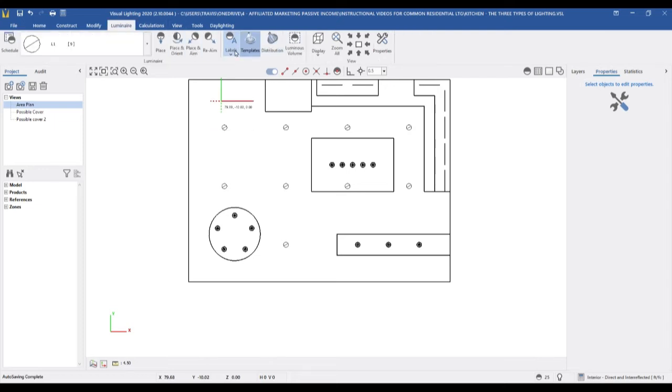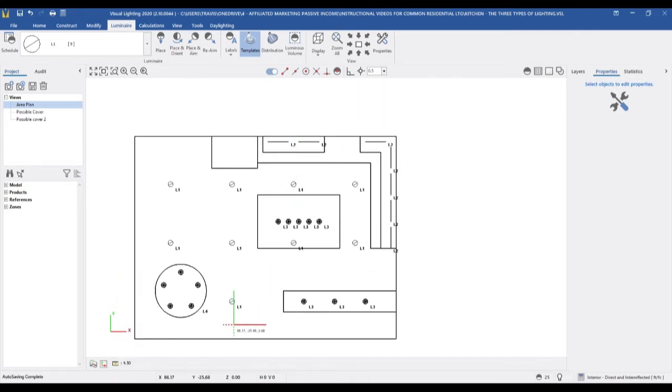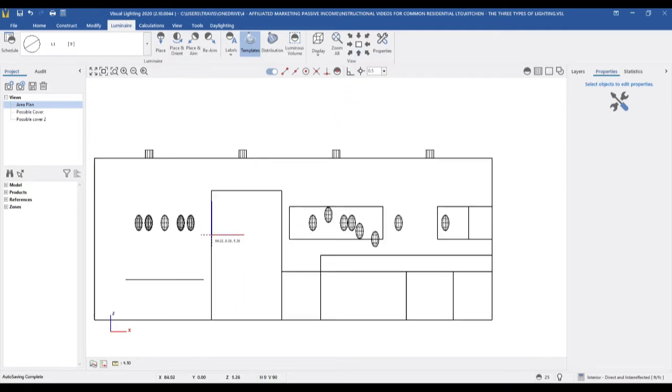If your ceilings are shorter, I like to use 4-inch just because the smaller aperture will make it less noticeable, and it will also help reduce glare. Also, if the light source itself is recessed more up into the ceiling, that will help reduce glare. Or if you have really high ceilings, then glare is not really going to be an issue for you because it's more relative to how low the ceiling is and how powerful the light is.